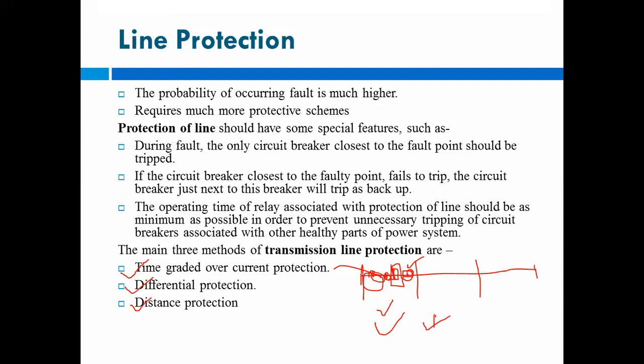And the last point is line protection. We have to protect the transmission line. For the protection of the line, we use the time graded overcurrent protection system, differential protection, and distance protection.